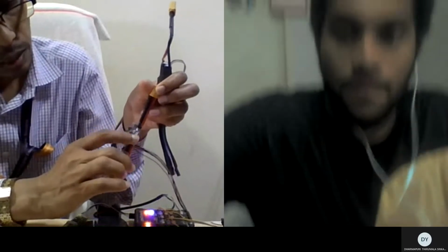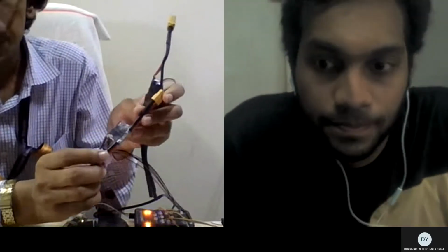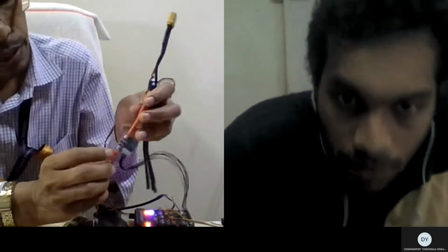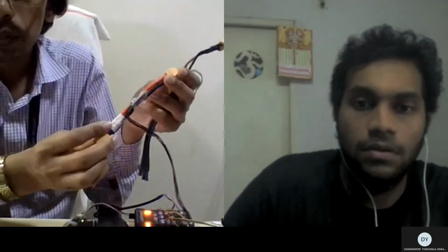If anything happens, there will be melting here. Okay, this is the soldering part. I don't know if you are able to see or not, but these are direct connections. This also has one diode. Okay, if anything happens here, this will get burnt. So it is actually protecting here. But if this fails in the air, the whole aircraft will fall down. Okay, so that is one constraint. If you don't have a power backup, then if the power module itself gets damaged, your ESC is good, your motor is good, but your power module melts because of the temperature, then I think we are losing the whole aircraft.